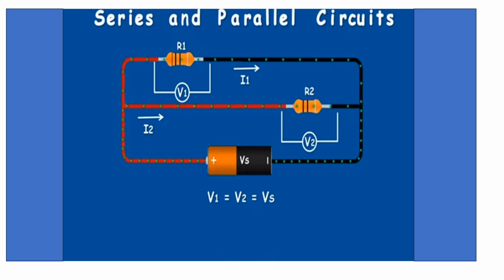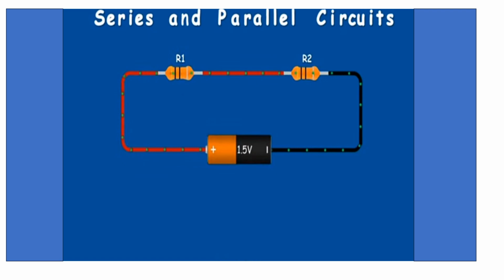So for the parallel arrangement, the same voltage is across them. So what we are going to do here is very simple. We shall use the same voltage, if it's 1.5, to help us find the current through each resistor given the known resistance. And just in case you do not have the other resistor, for this case R1 is not known but R2 is given, so I will use the same voltage to determine that.